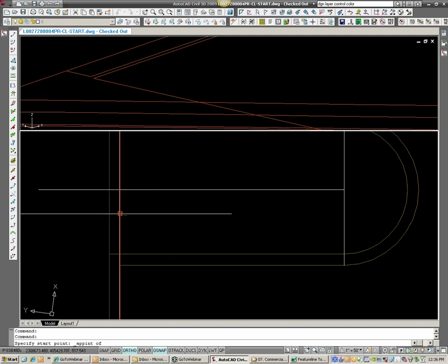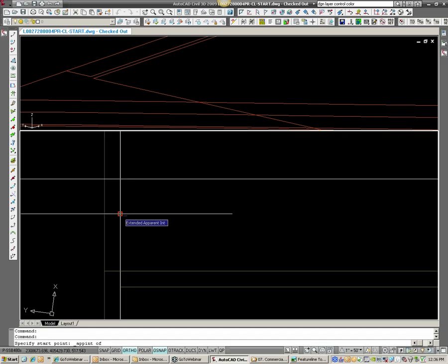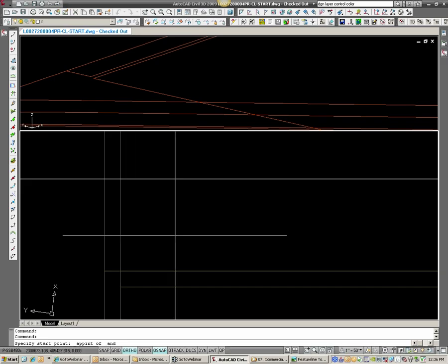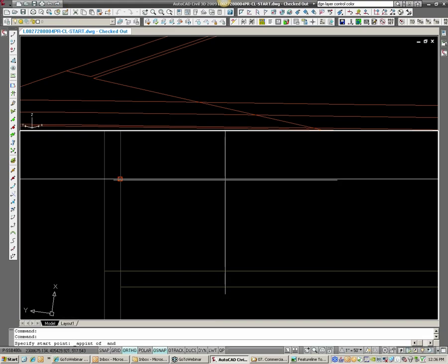The first line I use, that's where it's going to pull out the elevation. So I need to hover over a piece of line work, and you can see closely there, I get a square and 3 dots. It's going to pick that line work, but it doesn't snap anywhere because it's saying the apparent intersection. I pick the line, it says, the pick I made, and then I'm going to use that construction line work I used. So hopefully that makes sense because you have to use the apparent intersection command a lot.